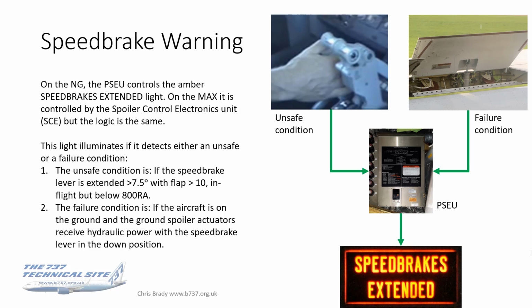The failure condition is if the aircraft's on the ground and the ground spoiler actuators receive hydraulic power with the Speedbrake lever in the down position. So that's the failure mode.